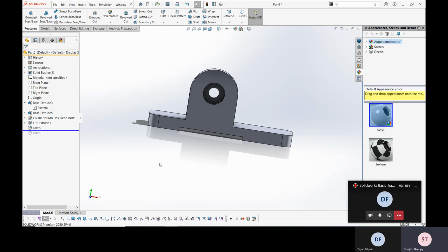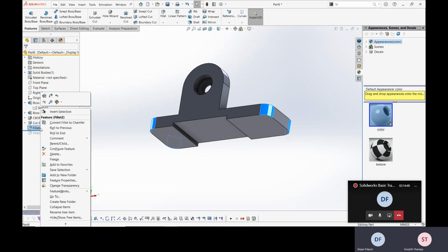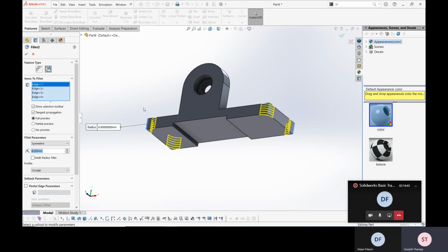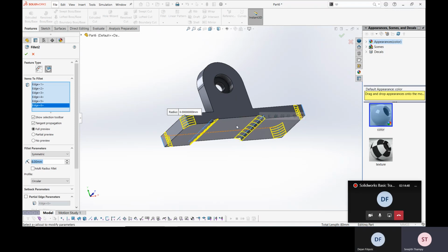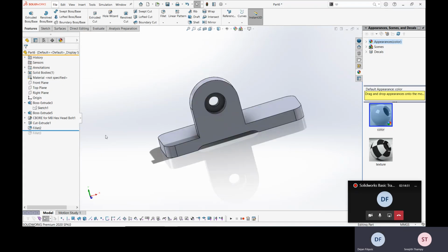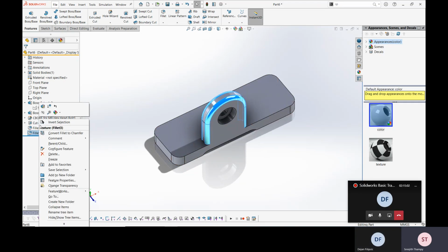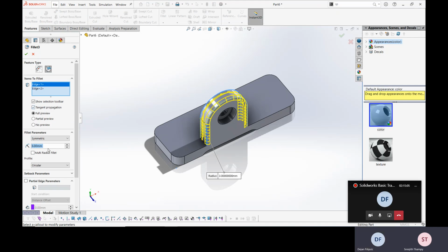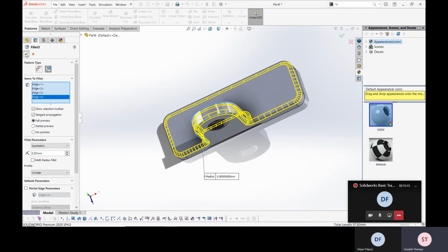So I have added the next fillet. So now I remember, I wanted this fillet here as well, right? I can edit a feature after it is created. I can add fillets to that. I can add commands to that. And I also remember that this needs to be traveling all over this. The fillet needs to be propagating all over here. It is not propagating, so I will go back and edit that as well. I wanted to add this. I selected one edge and it automatically identified the tangent propagation and it propagated.